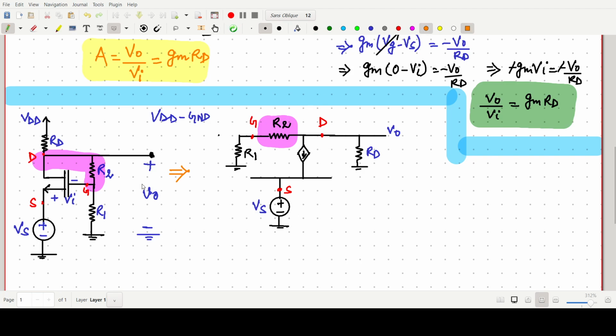And this voltage is nothing but simply your plus or minus Vf, feedback voltage. I am also highlighting this part. Gate is connected to ground. So gate is connected to ground here. Clear. So we are just making the AC equivalent model first. It is a very good problem. Then what we can say, this voltage is nothing but simply your plus or minus feedback voltage Vf, that we have to determine.